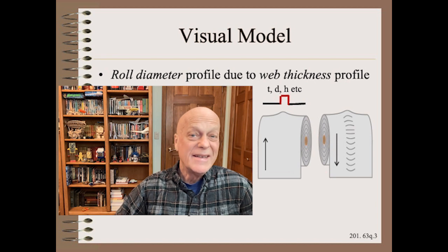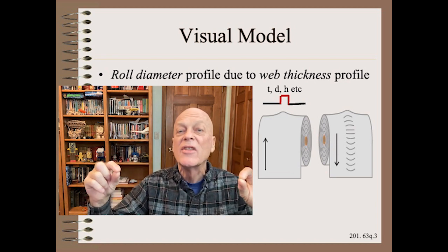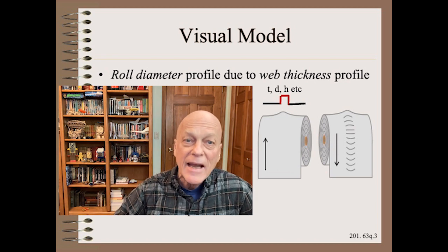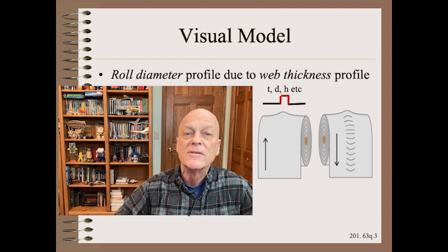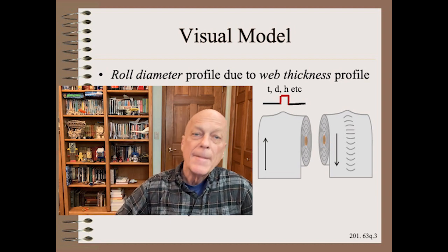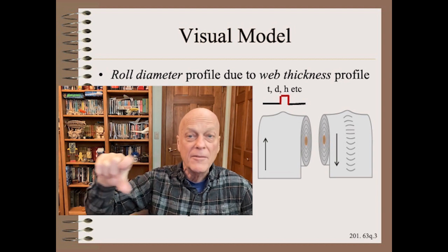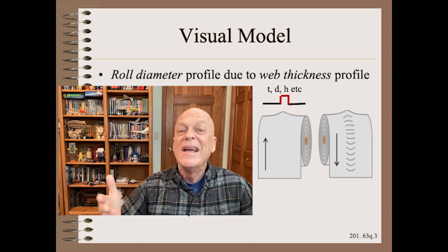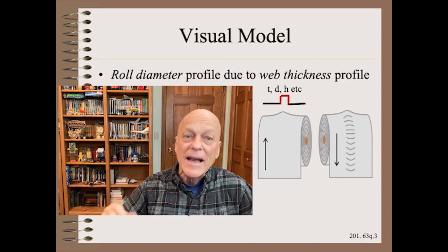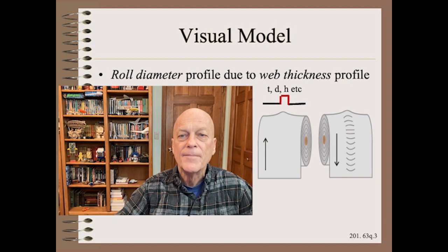The web then gets differentially stretched and yielded so that the outcome is a baggy lane where the web is slightly thicker than its neighbors. In short, the incoming web is flat but of variable thickness. However, when unwound, is longer and thinned at the areas of greatest local thickness.